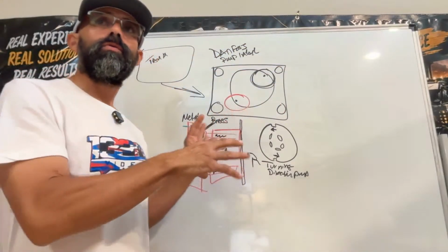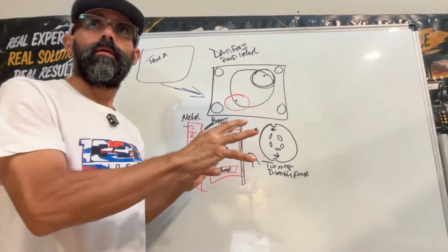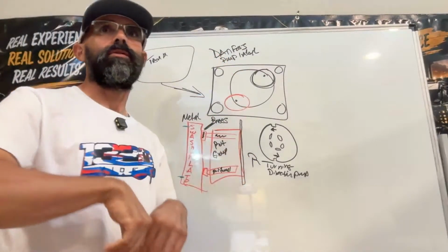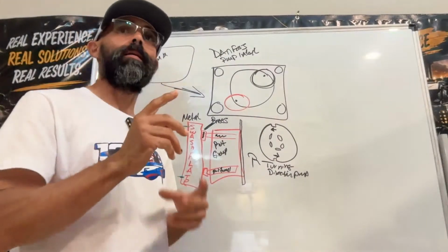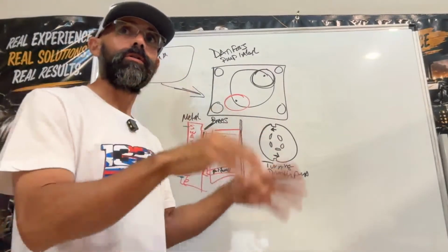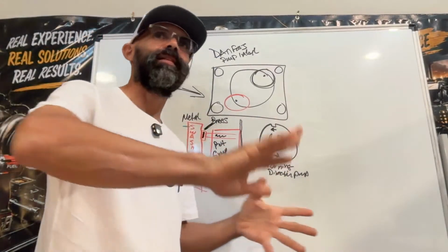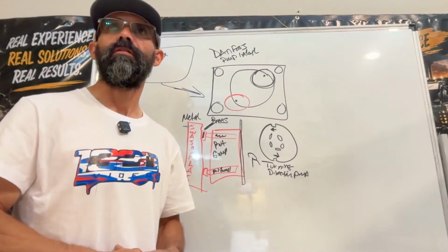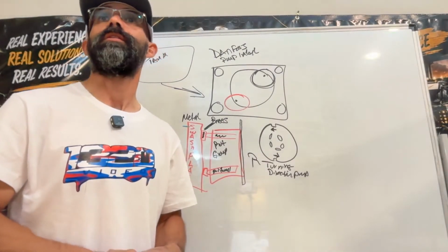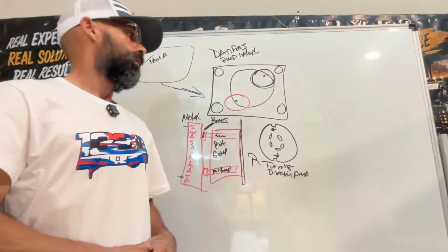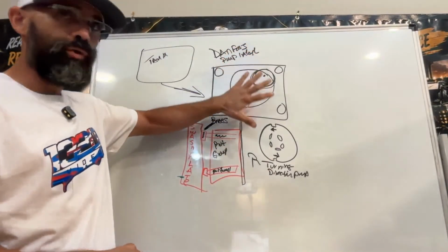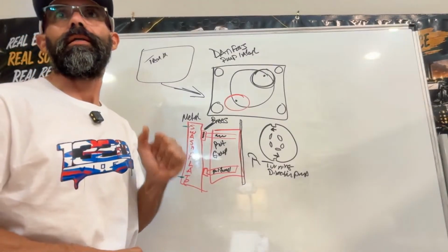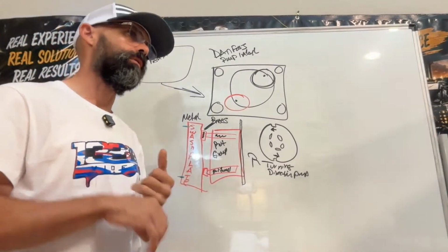So when it comes to a catastrophe like this, where something ended up in the pump and destroyed the whole pump, before I install the pump, I flush everything. And believe me, you're going to find a lot more stuff in the system. So when you do this, make sure you do it and clean it completely. Don't cut corners, because